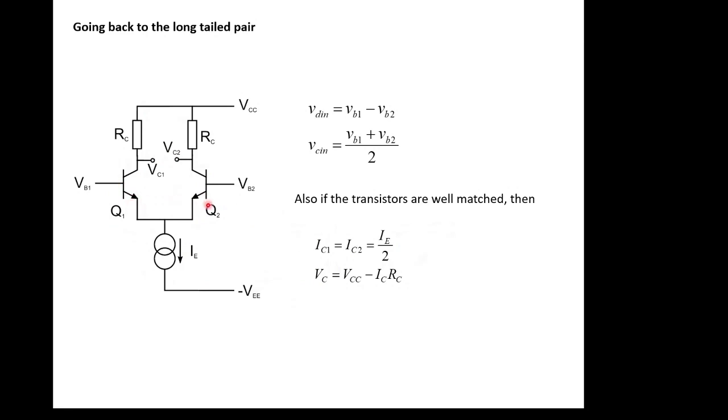Everything is affected by temperature, but temperature becomes a common mode signal. Yeah, the variation in temperature causes the signal to change equally in both sides, so it's matched out. To recap, does well matched mean they share virtually the same characteristics? Yes. Well matched is a euphemism for identical.